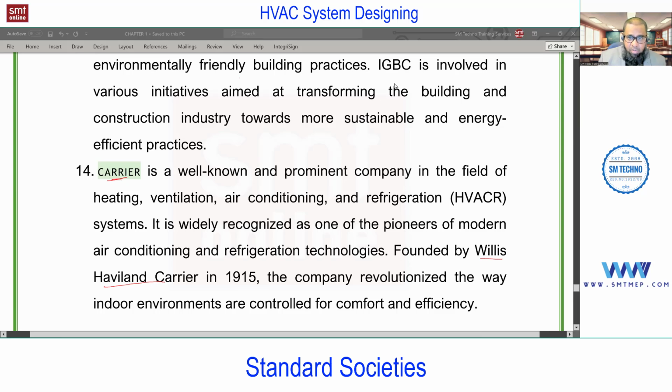And from Carrier, HAP, Carrier HAP, is commonly used in actual practice for load calculation. So you'll find the Carrier standard. Now in many areas, Carrier is following the ASHRAE standard, and in the Carrier handbook they also refer to the ASHRAE standard. ASHRAE is the society completely on the development side, but we cannot ignore Carrier also. For manual load calculation, we still use the Carrier standard. For pipe designing, water pipe designing, even in the ASHRAE handbook you'll find references from Carrier.